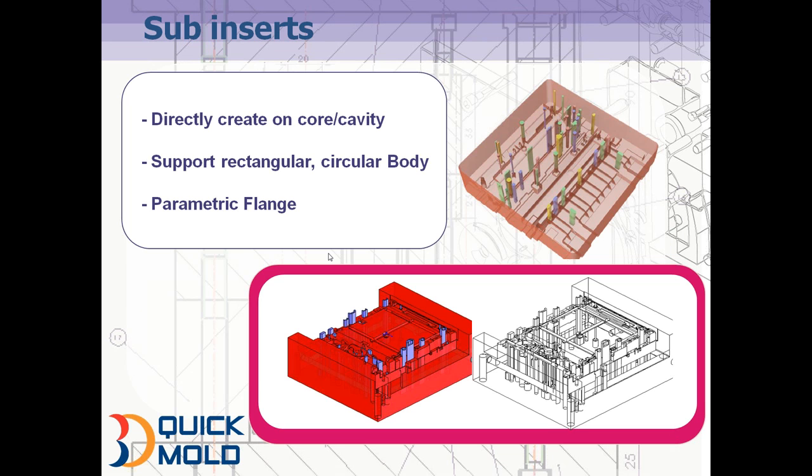I would also like to highlight a few more things, like sub inserts, which are also a part of this. For every core and cavity, a few complex areas cannot be manufactured directly. There are some ways to create local inserts and sub inserts so that we can make our work easy. So this solution offers you the ability to create individual inserts also. Any profile directly on the screen itself you can convert into a local insert or sub insert.